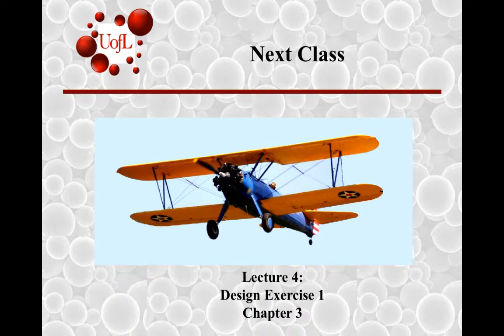So in this class, to summarize, we have looked at a number of property charts where the x and y axis are varied over a large number of properties, both directly as well as derived as a product of multiple combinations of properties. These help to look at selecting the best material or comparing an existing alternative with something that could be better. So this is the story for week 1 in terms of a background for material selection.